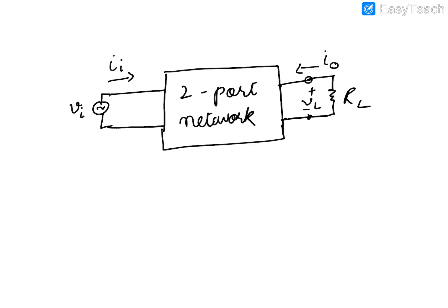So this is a case of a loaded amplifier in which we have connected a load across the output terminal, and you can see that the input current direction is from negative to positive, or the input current is leaving the positive side, and also the output current is leaving the positive side of load voltage. So you can see their direction is opposite, so in this case we can anticipate that the current gain will be negative.